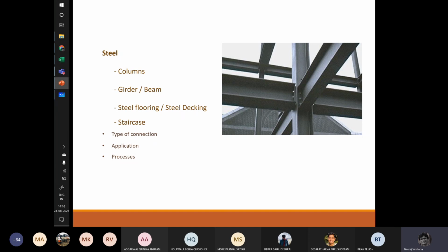If a wooden railing or wooden balusters or something for the handrail comes, then that you will calculate in timber. I hope you get it. Okay, wherever the material comes, you have to keep your eye open in your own structure. If you haven't considered it, calculate it and keep that in your mind, so that when it comes to the item or the material, you mention it.